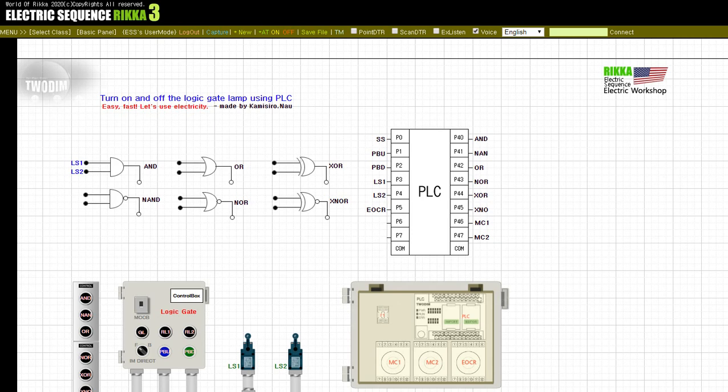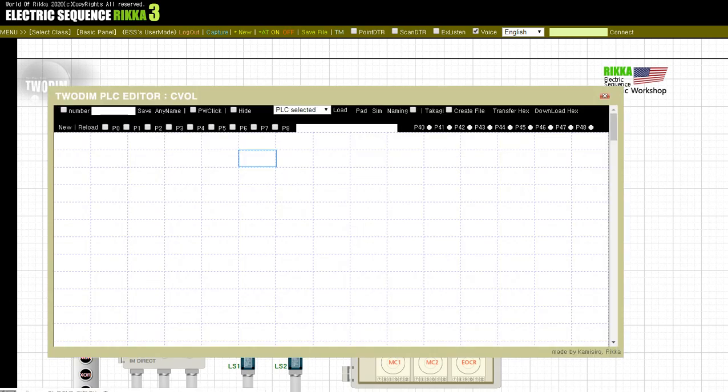Now turn on the power and check the operation of each component to see if it matches the above. Please check the motor operation according to the input through each push button and limit switch. Also, look at the direction of motor operation according to the SS selector switch. Before checking the simulation operation, take a moment to look at the program configuration of the PLC. The composition of the PLC program may differ depending on the user. Please refer to the written PLC program configuration.